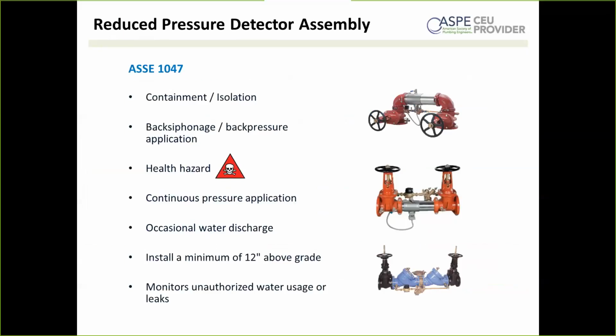How can a 4-inch drain accommodate 320 GPM? Yeah, I based that off of a drain calculator that I found. I will admit to not being a drain expert. I found some calculator online. So that's also based on an acceptable amount of head. I figure usually your mechanical rooms, they have a lip in there, built into the concrete that's a few inches high. That's going to give you some head pressure to help drain. But every situation is different.